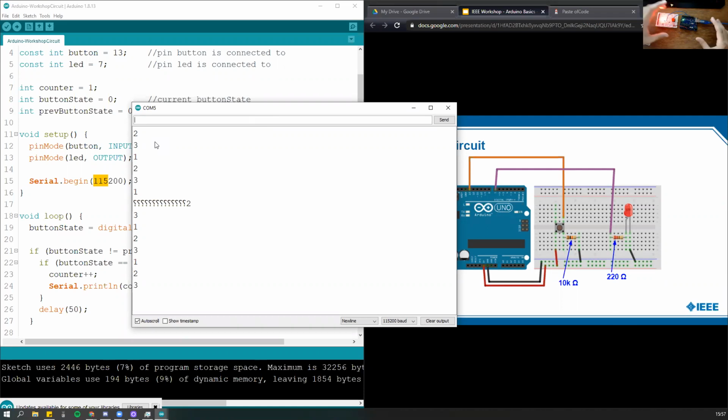I had an Arduino connected to a big switch, which was a piano key. And when you pressed on the key with your feet, it would send a high signal to the Arduino, and the Arduino would output that to the serial like this. But instead of numbers, it'd be letters. And then I would have a program on my laptop running Java, which would read from the serial and play the musical note associated with that key. So it was a giant piano, but with Arduino and Java and your laptop. So it's pretty cool.